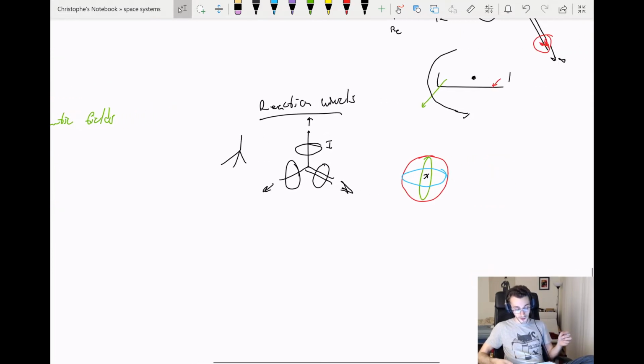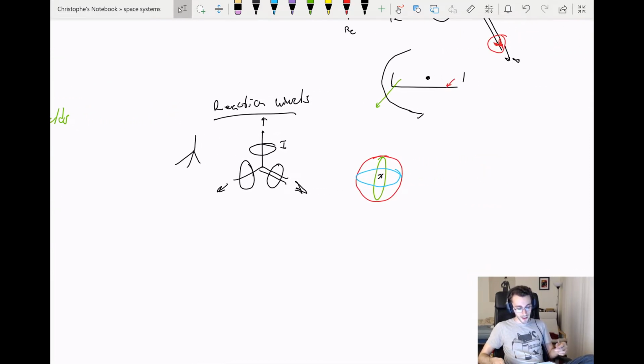I mentioned saturation. So what is saturation? A reaction wheel has a maximum speed. If you take one reaction wheel and spin it up to its maximum speed, your space vehicle is spinning in the opposite direction at the maximum possible speed along that axis. If you don't have any other control systems on board, and you're in deep space with no gravity gradient, no solar wind or anything like that, there's nothing that will change your attitude aside from this reaction wheel.